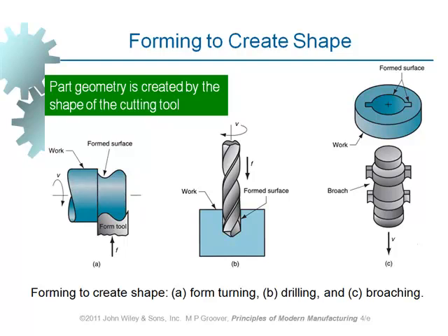Okay? So the one that we had in the previous slide, the hole with a number of slots on it, can also be made by making use of the broaching process. However, the number of cutting edges will be more. This method costs us much less than EDM. Much less than EDM. Because a physical process is used in order to cut the material, which often costs less than chemical or electrical or other forms of energy. Okay? It's interesting, isn't it? Broaching is a very interesting machining method. Anyway, now let's compare these ones with the ones that we had in the previous slide.